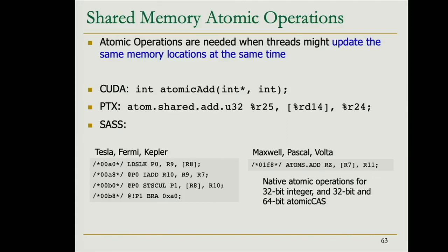And also, if you look at this, you can see these P0 and P1, which are predicate registers. You remember, we have talked about predicated execution, right? Essentially, this predicate register is one single bit per thread. That's enough, one single bit per thread. And what we're going to have here is 0 or 1, depending on whether the thread succeeded or not while trying to lock the access to the particular location in the global memory, in the shared memory in this case.